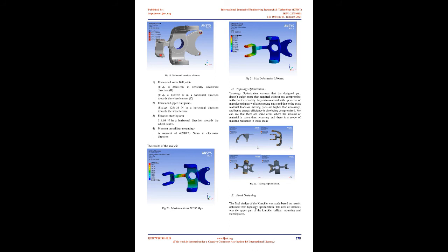Calculation of forces on the steering arm. The steering axis intersects the ground at some distance from the point of contact of the wheel. This distance is equal to the vector addition of scrub radius and caster trail. Due to this separation, the net frictional force causes a moment about the steering axis, and this moment is balanced by a force acting on the steering arm of the knuckle.